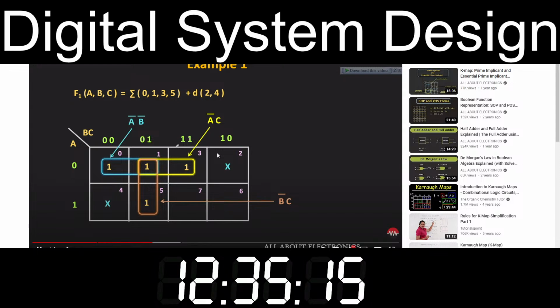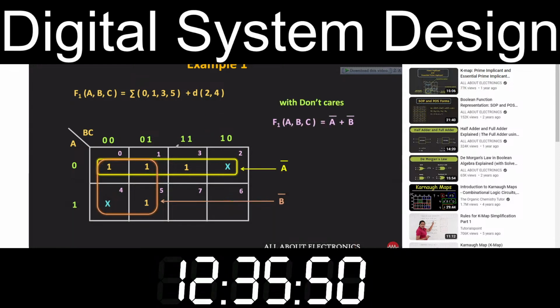So this group corresponds to b bar, while this group in the yellow color corresponds to a bar. And the overall minimized function is equal to a bar plus b bar. So in this way, using the don't care terms, we can further simplify the Boolean expression.